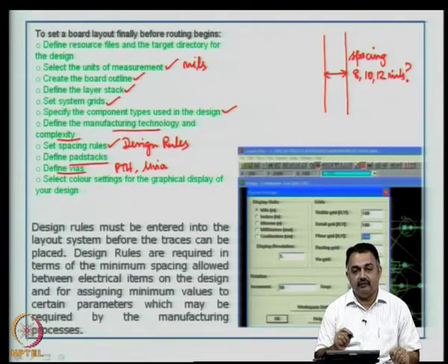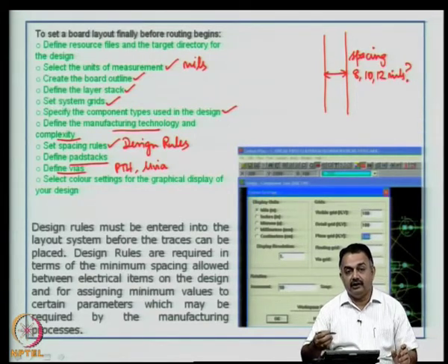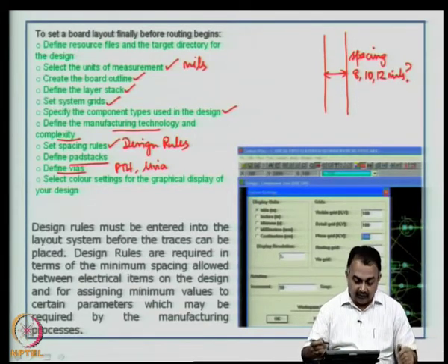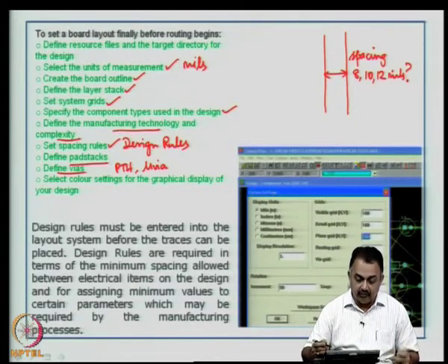In each case, what is the size of the vias that you are going to use for different areas in the board? It need not be uniform via size across the board. You can vary the via size, let us say for a through hole via from 600 micron to 200 micron, 0.6 mm to 0.2 mm depending upon the design and the electrical requirement.